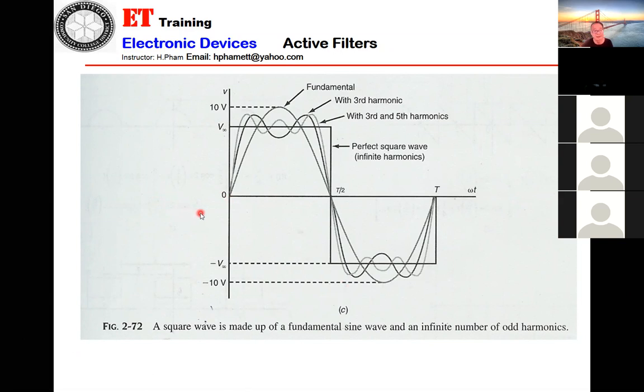So basically, when they ask what the bandwidth of the 1 kilohertz square wave is, you know the minimum is 1 kilohertz. However, you don't know what the maximum is. So you have to ask them, okay, you want a 1 kilohertz square wave, but up to what harmonic?